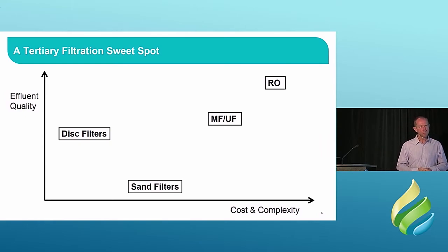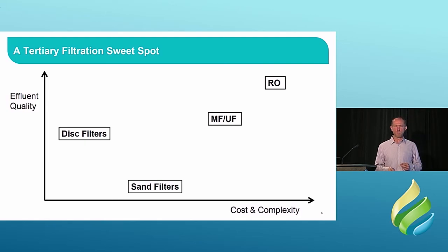Okay, thank you. John has a question here. How long before you have to replace filters, and how high of TSS can they handle and for how long? So what's your maximum loading? Good questions. How long does vary between different manufacturers. I mentioned before that we have offered filter cloth guarantees up to 20 years. To be clear, that's a pro rata guarantee. It's a lot like a membrane guarantee, if you're familiar with those.